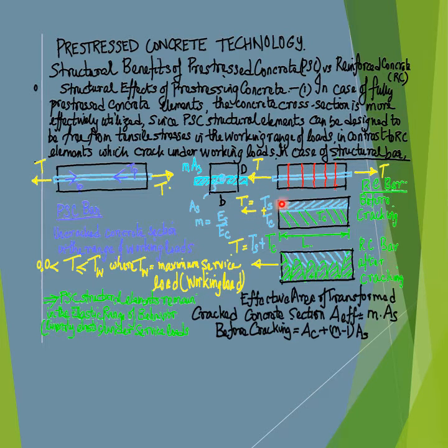With the sum total of the share of the externally applied tensile force resisted by the concrete in the uncracked reinforced concrete bar and the share of the externally applied tensile force resisted by the concentric steel bar, denoted as capital T subscript S, proportional to the axial tensile stiffness of the concentric steel bar and the concrete section.